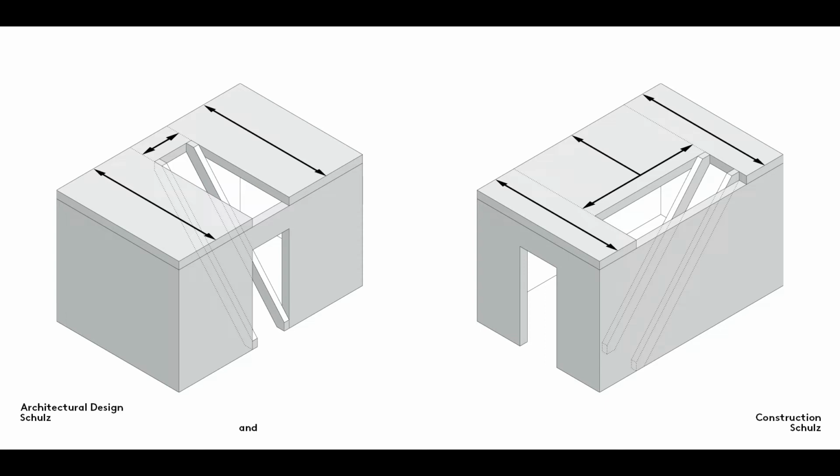When the stairs are set parallel to the span direction of the floor, there is no change in the situation of the floor spans adjacent to the opening. There is only one section spanning the width of the stairs where the load-bearing conditions change. The situation is more complex when the stairs are arranged at right angles to the span direction. Here, the greater part of the floor is no longer supported on the wall, and so time-consuming steps must be taken to divert load transmission.